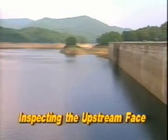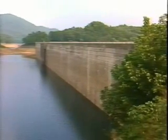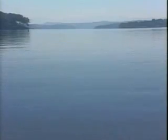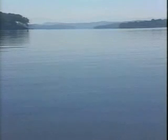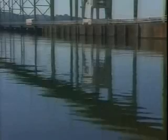Now let's turn our attention to inspecting the upstream face. In general, you will want to schedule your inspection when the reservoir level is high, so that you can see how the dam responds to maximum load conditions. However, a high reservoir level usually means that only a small part of the upstream face can be inspected.